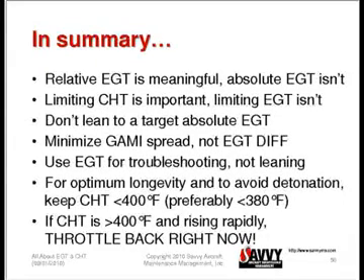So just to summarize some of the stuff we've talked about here, relative EGT is meaningful, but absolute EGT is not meaningful, so let's not get hung up on the numbers. Limiting CHT is important, limiting EGT is not important. We don't want to be leaning to specific EGT targets like some people are taught to do. It's just not a good idea.